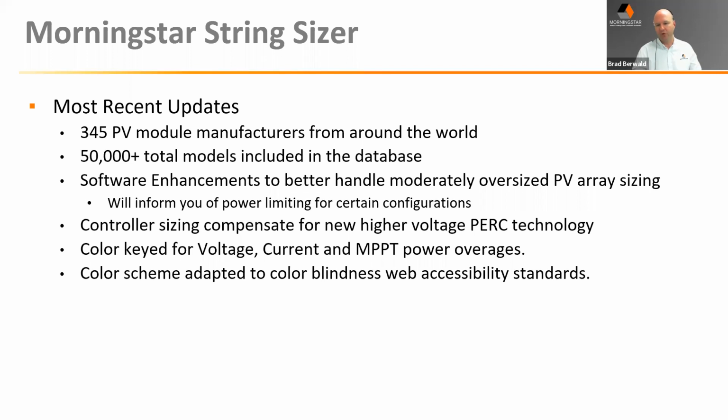We're also, while they've been out for several years now, seeing half-cell modules, and some half-cell modules that are being cut and doubled, have caused a few changes in how systems are designed, and we've taken that into account with our String Sizer so that they can be adequately sized. We've got to keep up with the changing trends in the modules, and these new kind of hotter cells that have a little more voltage than they did in the past require a little bit of a tweak.